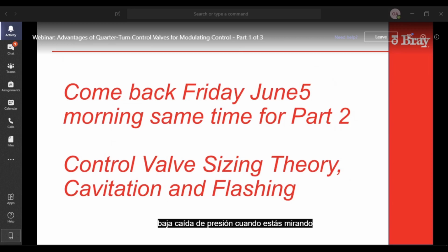When you're looking at anything beyond half of the inlet, you're looking at higher pressure drops and possibly then the more expensive type of control valves. It depends on what the fluid is. If it's liquid, it depends what the fluid characteristics are, what the vapor pressure is. But then it also depends on if it's a compressible like a gas, how much velocity. Even if you take a 30% pressure drop out of a very compressed gas, say 1,000 psi gas, you're going to get a lot of velocity, and that's another consideration that'll result in noise.